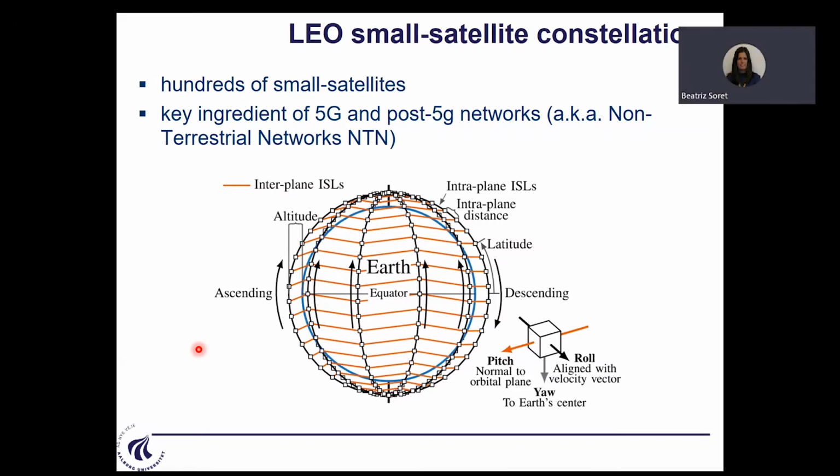The intersatellite link, the ISL, is not always deployed. That's true, because it's expensive to do it. But for missions like Starlink, these big ones that are coming, that have the ambition of being global internet provision and very general purpose missions, they have to implement it, because if you have to guarantee any latency and any end-to-end performance, then you need to deploy it. But it's true that there are other simpler missions that just have the traditional link to ground, and that's it. Then you have to wait until the satellite reaches the destination.